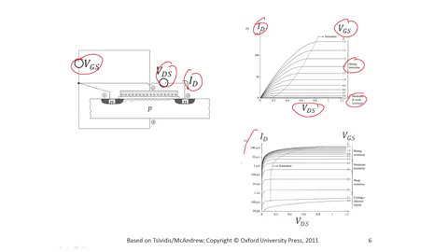and now things look like this. We have expanded the low current region, and now we can clearly see the weak inversion region here, the moderate inversion region, and finally the strong inversion region. In fact, we have such resolution for low currents that we can even see a region affected by leakage. And by leakage, I mean the leakage current of this junction. The PN junction here is reversed biased, and there is some leakage current associated with it, which we will discuss later on.